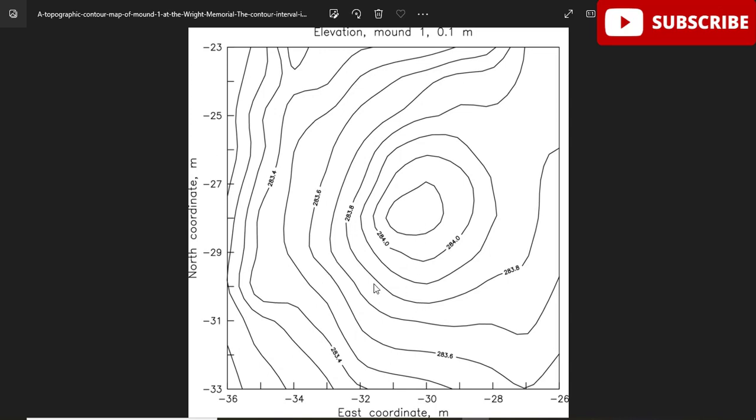So I have a map. For example, you can see we have contours and the contours are at a 0.2 interval. You can see the interval must be shown on some contours, which we will apply later, and some other dimension, any one line has a dimension. It can be in feet or meters, it's not meter here. So we will convert this map into contour surfaces in Civil 3D. So let's start.